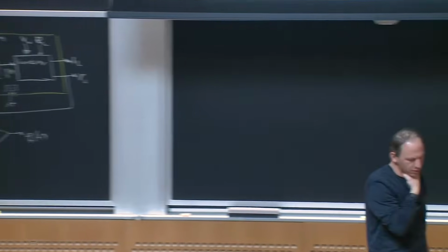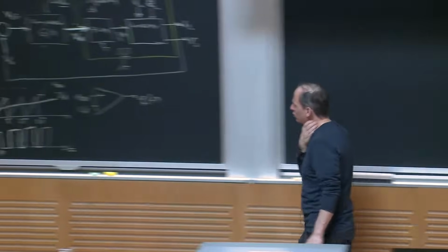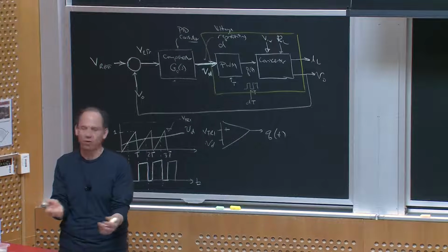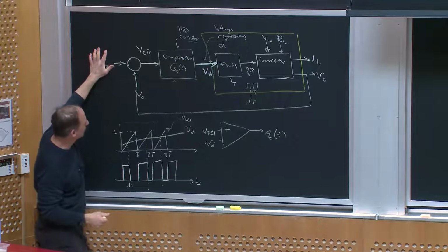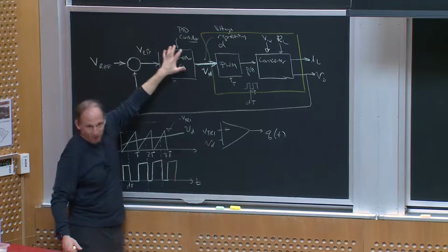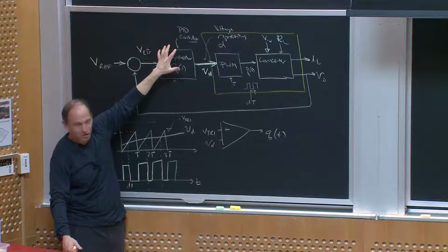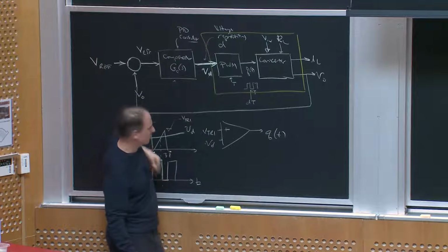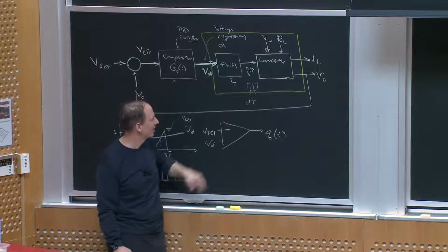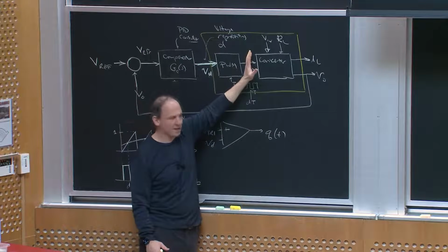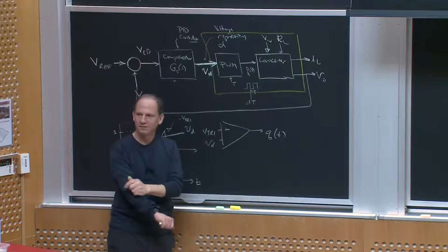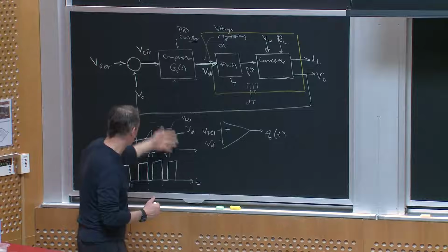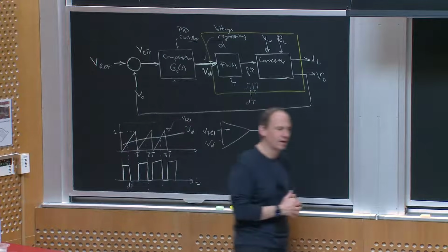All right, so that gives me a way to implement this. And I should say, by the way, that if I go buy a PWM chip for a typical DC to DC converter, or a controller chip, I'll usually get a reference, some kind of error amplifier, op-amp, and other things to generate the compensator. I'll get the PWM chip, and in fact, this triangle also serves as my clock, so I can set the clock frequency, I can set T. And then, maybe it gives me a gate driver. So I'll get all this stuff in one chip very often for a simple design. Okay? Of course, you can also do a lot of this stuff digitally these days, depending upon what kind of processor you use.